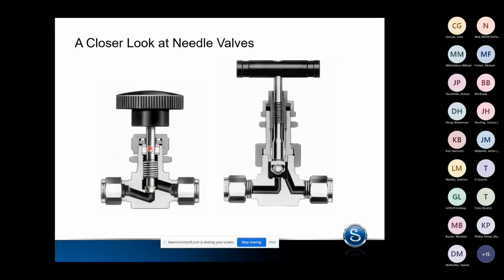So as you try and tighten this valve more, you're grinding this sealing surface together. So we create a galling force. So be careful. The handles are designed so that we don't over torque the valves open or closed. But the ball is able to rotate so we're not creating a twisting force during shutoff.